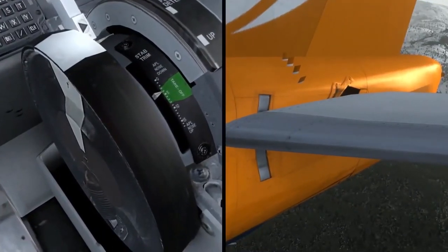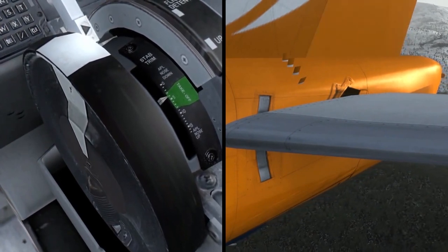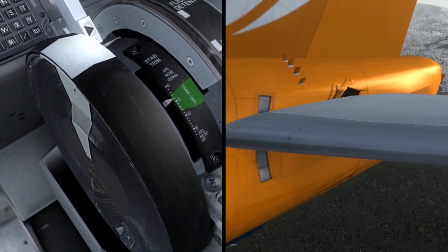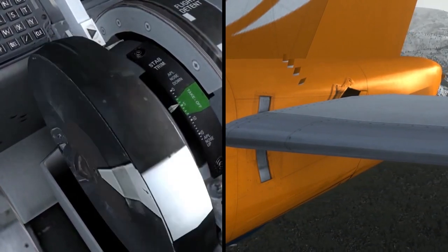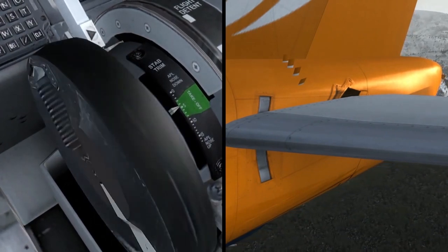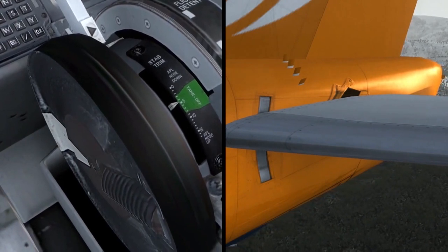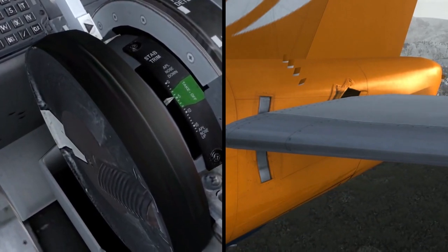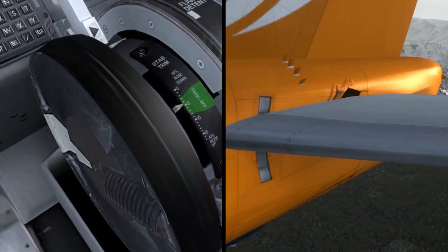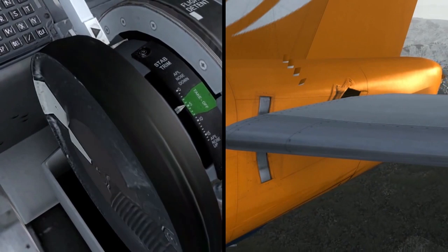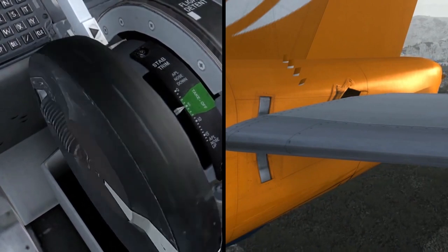During electric operation, the pilots operate 4 stabilizer trim switches located on the outboard side of each control wheel. These control electric input to the stabilizer trim actuator that also moves a mechanism with a jack screw. Like we mentioned before, when the jack screw moves, the stabilizer moves. The system is made so that when the electric stabilizer switch is operated, the horizontal stabilizer is moved, and so are the stabilizer trim wheels. In case the stabilizer is trimmed to the end of its electric limits, additional trim is available through the manual trim wheels.